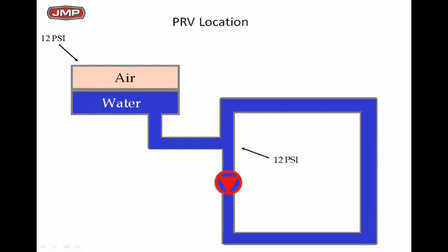And you do that if you locate the PRV where the T connection is, at the same location where the expansion tank hooks into the system on the suction side of the pump, which in theory should be the lowest pressure at that elevation of the expansion tank. So now you can dial in whatever makeup pressure you want minimum. It's on a location that makes sense. If you get below 12 pounds, it's just going to start makeup water. It's going to maintain that minimum pressure on your air control system of 12 pounds.